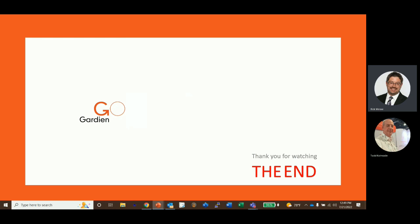I think the hour or two you'll take on a lot to do it is a lot less painful if something happens later on down the road, a week or so later, when you've got the board ready for final ET and then there's a problem with this sequential LAM step. That's all I could recommend. I can't stress that enough, Todd. There's more to sequential LAM test than AOI. I strongly recommend that you do ET on it as well.